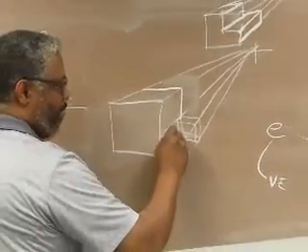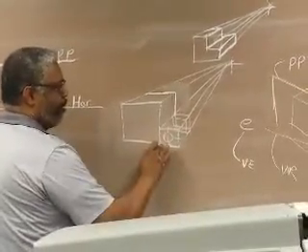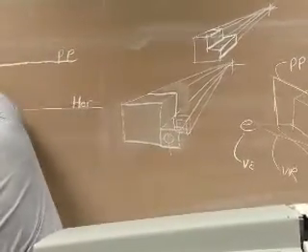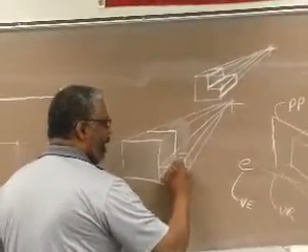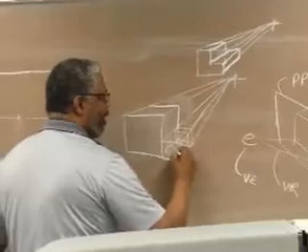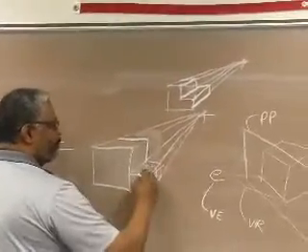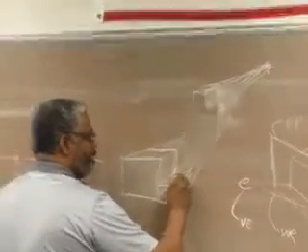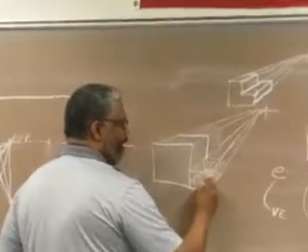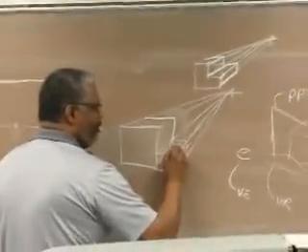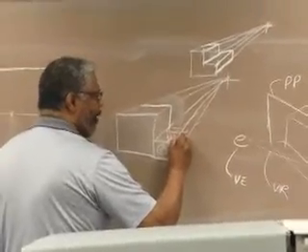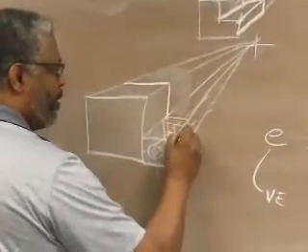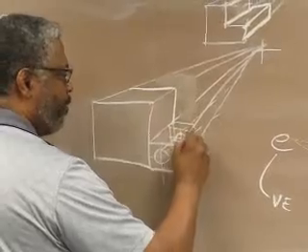Well, I also have the hole sitting true size on the picture plane right here on the orthographic view. But when I take the quadrant back, and locate the center of this and come down, I can take these back to where they would hit on the quadrant, and then use those points as a reference to construct another circle.